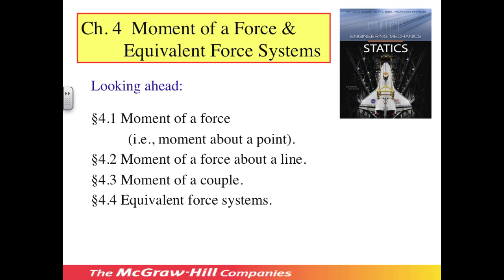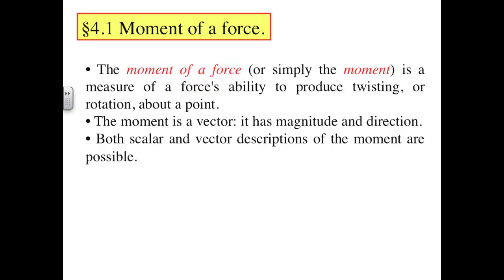We then discuss something called a couple, or a force couple, that produces a pure moment load. Finally, we close with a discussion of equivalent force systems. This last topic will turn out to be quite important to us because it provides a way to reduce complicated force distributions to their simplest possible forms.